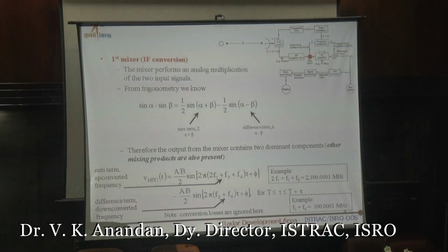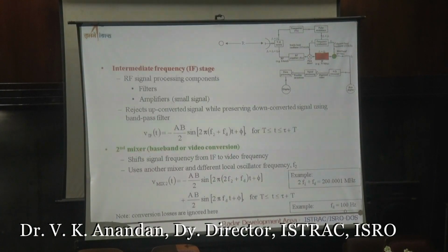Now finally, you have to get FD again. So we mix again with a signal that was used in transmission, in the second stage. You again get a higher component as well as a lower component. The very high order components we will not keep here; all of these will be filtered out. The filter comes into action to take out this signal. Finally, we get only one component, which corresponds to what we talk about.